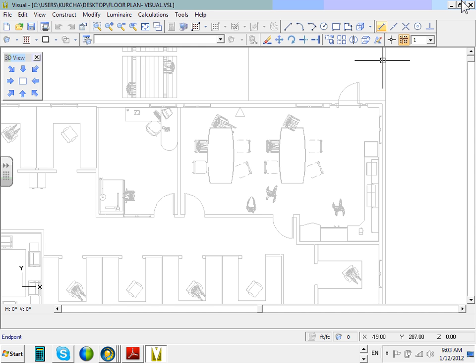Everybody, there are three things you need to be coordinating with. Number one is the location, lunchroom. What's the average foot candle? 25. What's the page number for the fixture that we're going to be using? 45. And then you're going to go to the 45 Lithonia book and look at which type of fixture we are specifying for this area. And this is a GT8. In real life, you're going to have a list of fixtures practical for different applications, and you can pick these fixtures right away.